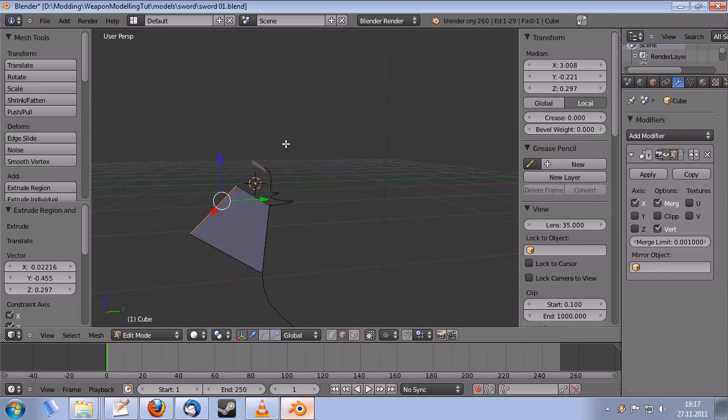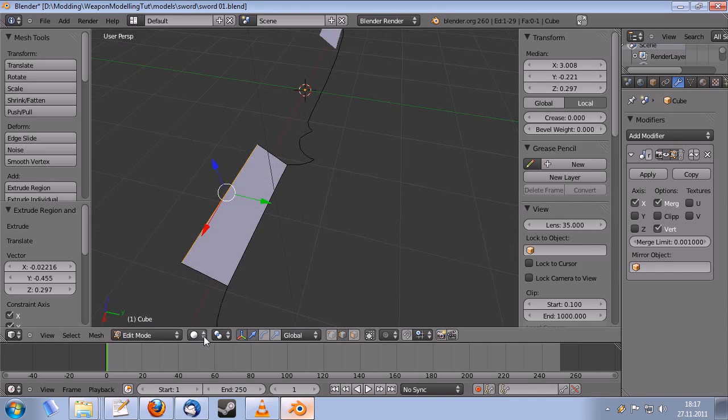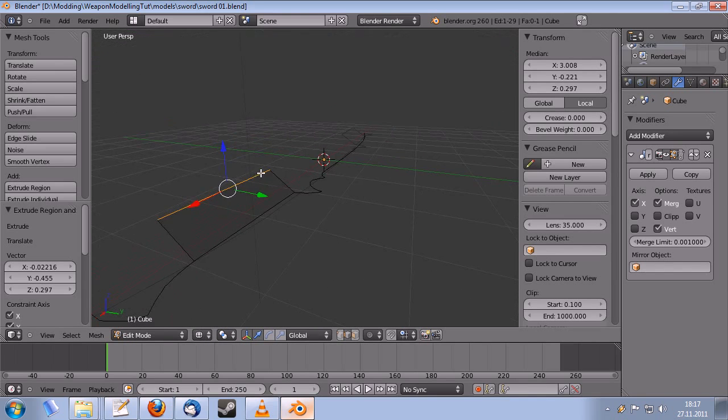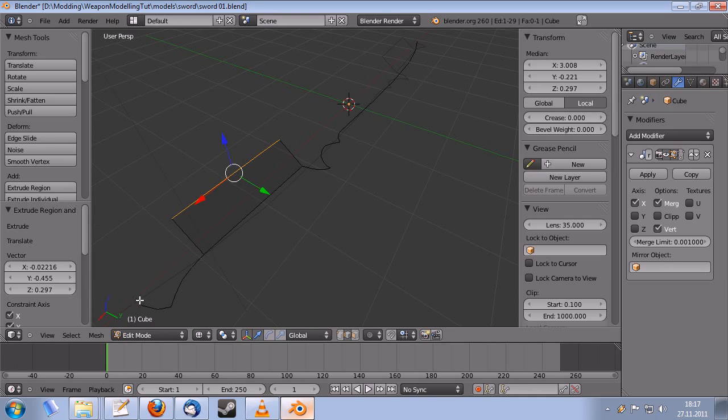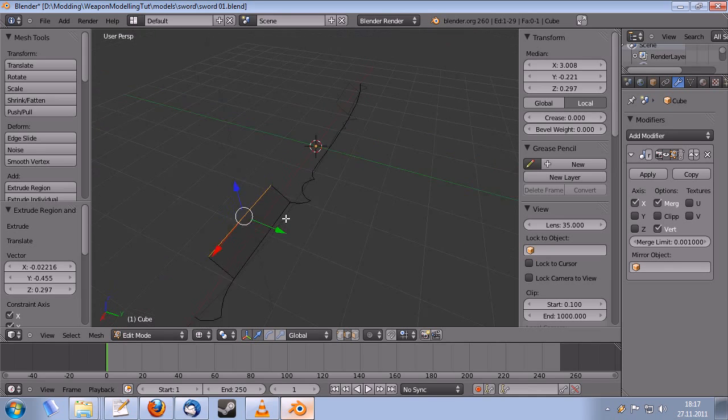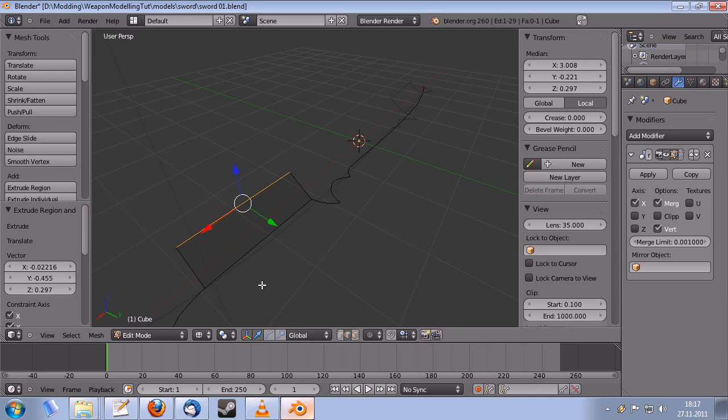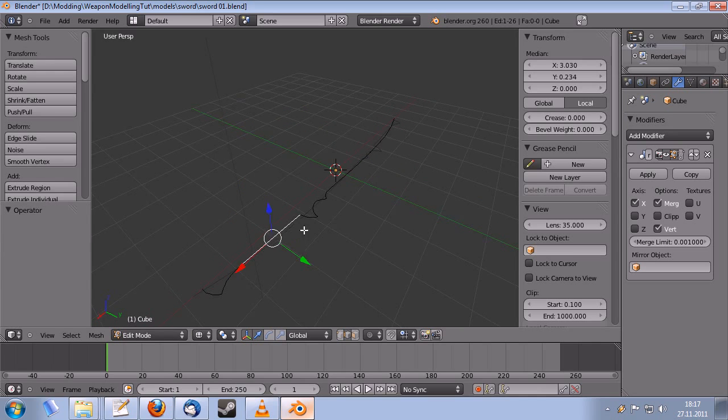This face is usually solid and you can't view through it unless you're in wireframe mode. Then it's transparent and you can see what's behind it. And also all the edges that don't make up faces are visible. So that's why I used it. But right now we don't want any faces yet, so I just undo that by pressing Ctrl Z.